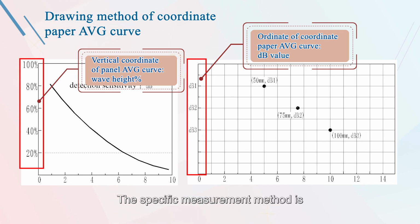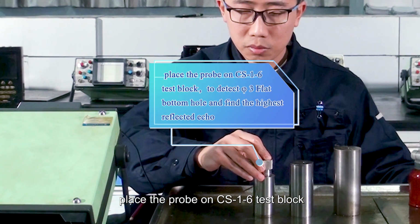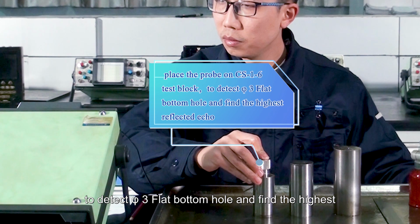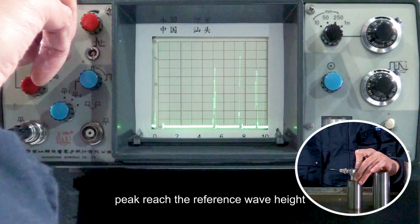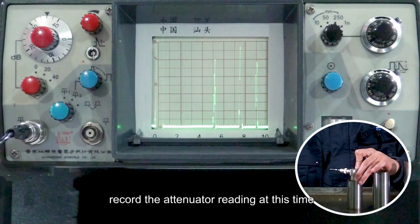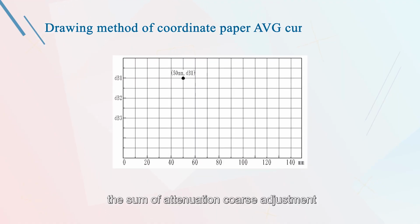The specific measurement method is to place the probe on the CS-1-6 test block to detect the flat bottom hole and find the highest reflected echo. Adjust the attenuator and gain knob to make the echo peak reach the reference wave height, such as 80%. Record the attenuator reading at this time, that is, the sum of attenuator coarse adjustment and attenuation fine adjustment readings, recorded as dB1.